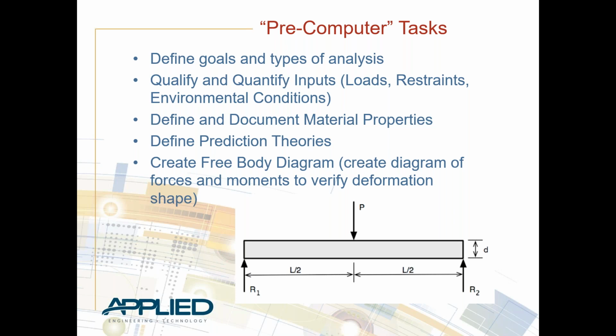That would be, what type of load is going to be applied? Is it on the appropriate surfaces? Make sure there are no point loads that could cause singularities in your model, where there's a super high stress that you just can't get to converge. What are the boundary conditions and things like that? What are the constraints? We build those in.